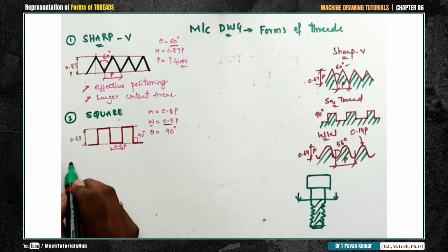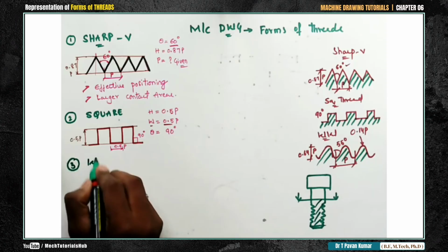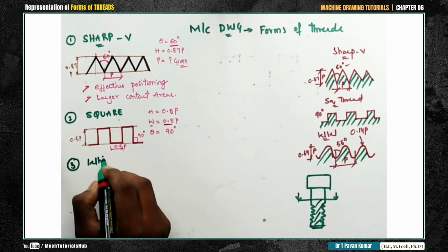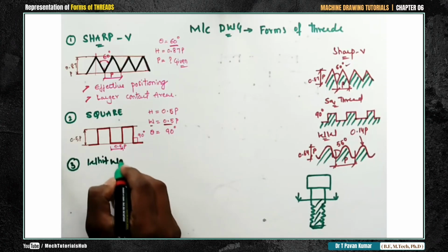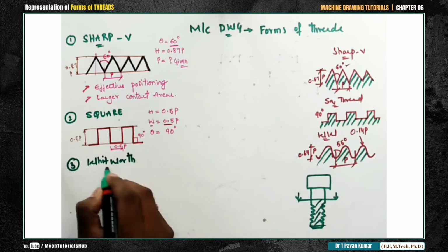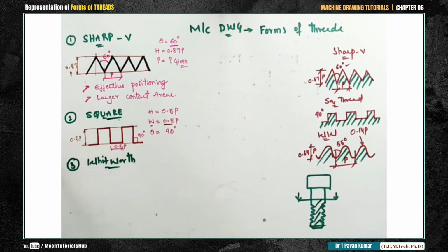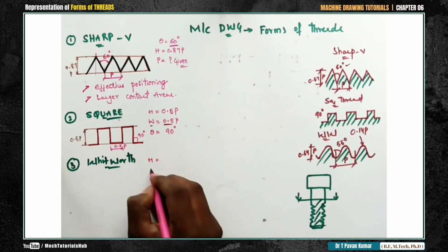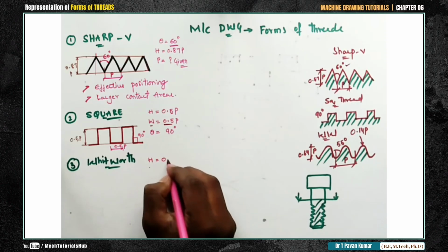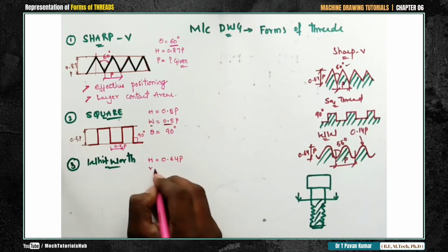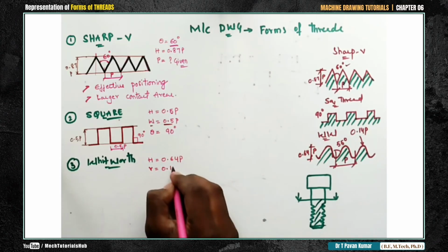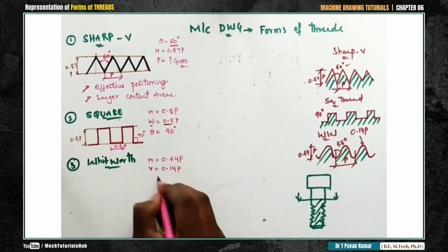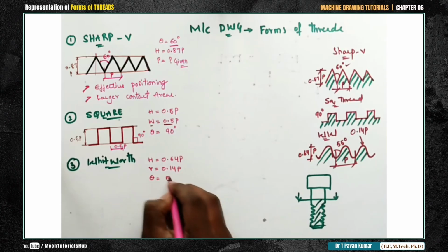After drawing this line, again make a mark somewhere on the above or bottom horizontal, and consider the r value, 0.14 p. On this vertical line, try to make a mark of 0.14 p. Calculate the value 0.14 p. From this intersection, make a mark of 0.14, and with that radius, draw the curve, a semicircle.